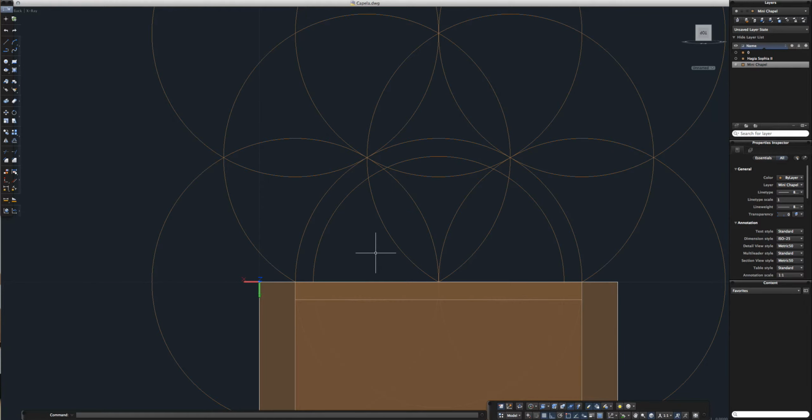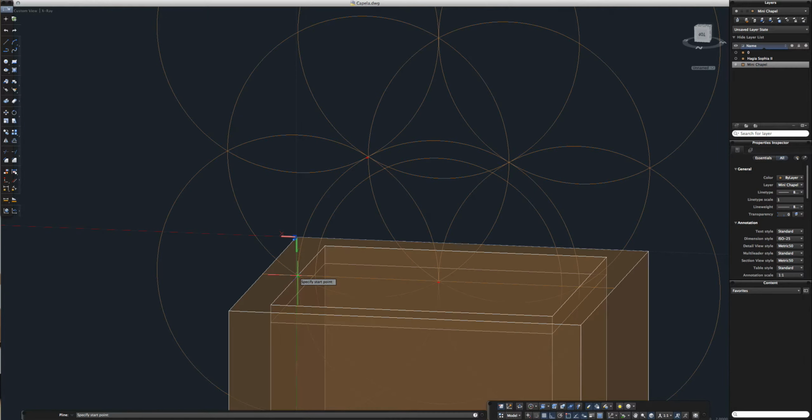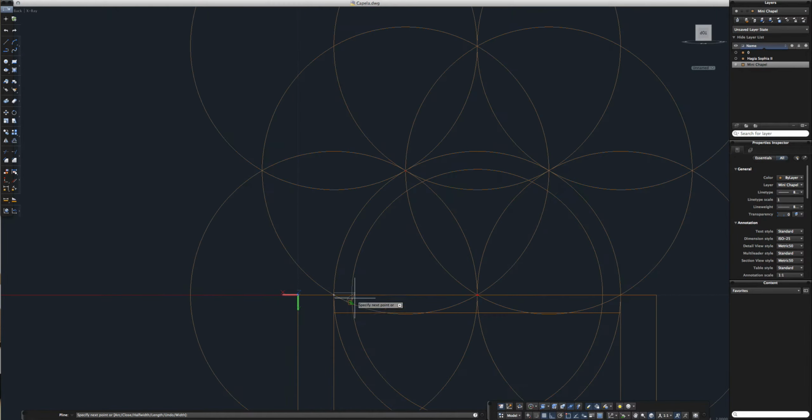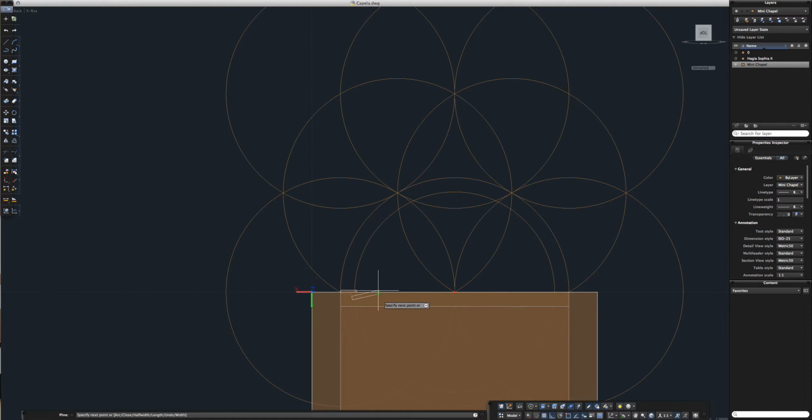Now let's use a new polyline, and this will be the trickiest part. Let's keep the width this time. And now let's select arc. Just write arc and then second, so we can select a second point about here. Then just push it all the way to the center.